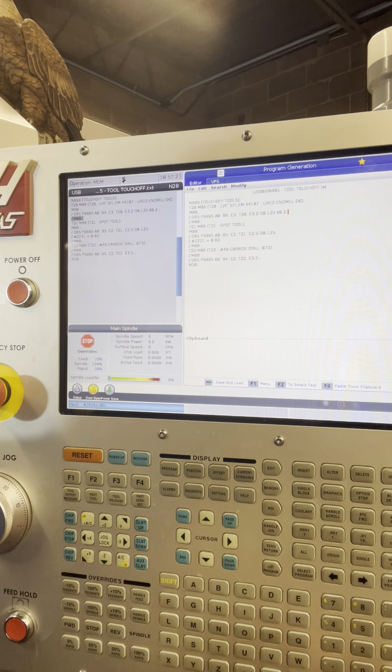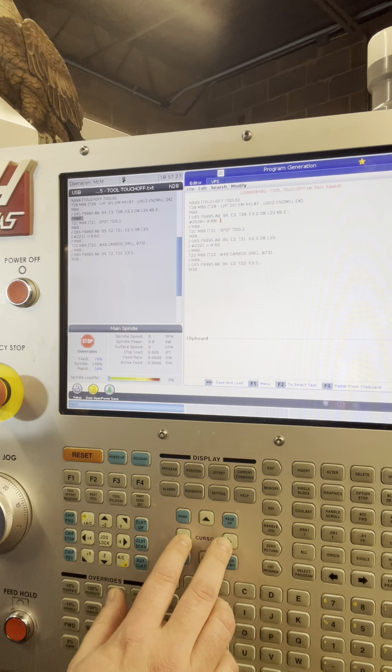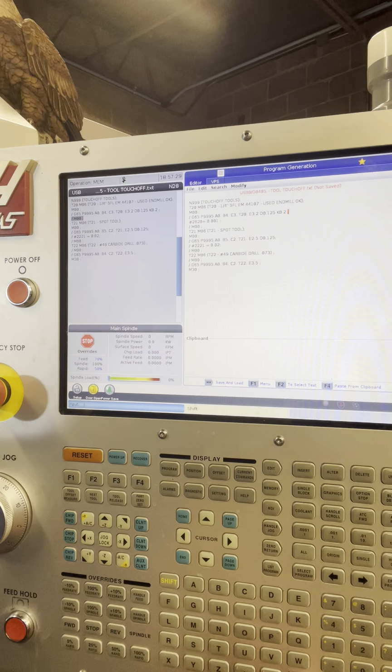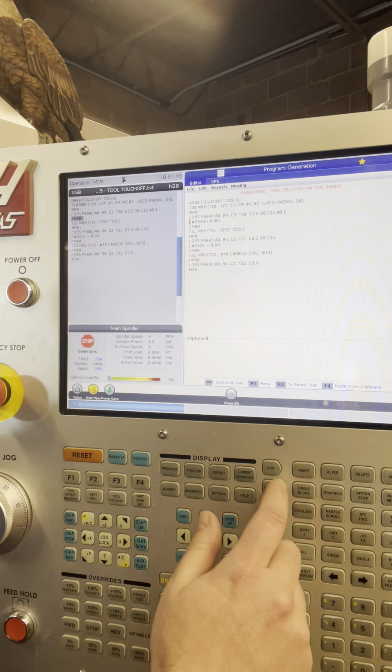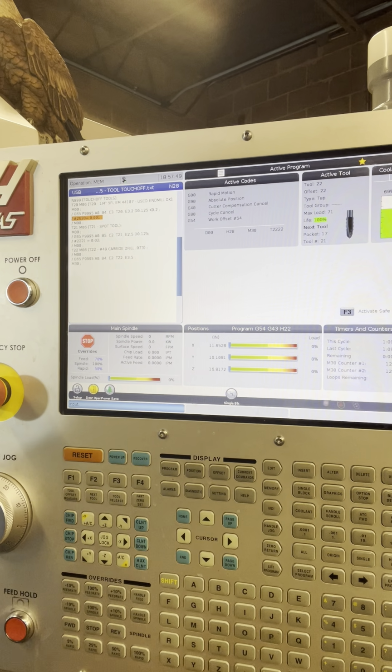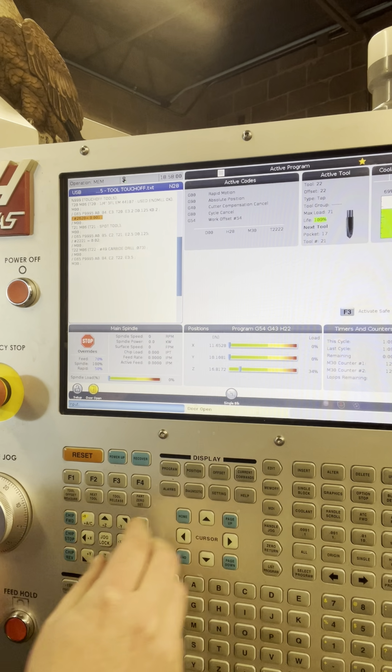a thousandths wear comp on there. And I'm going to put my block skip in front of there. I forgot that, but that way when we unload the tools, we're not writing it back into there, just in case you're running through and you wanted that number, you don't lose it. So when you run this single line of code here, I'll single block this. I don't like running other people's machines, but Brett's awesome. So I'll run this single line of code here.